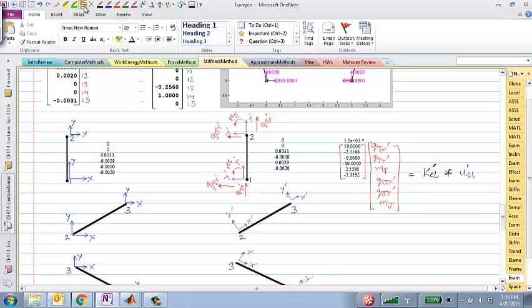Okay. So now that I have these 6 element forces and moments, how do I determine what is axial force, what is shear force, what is bending moment for this element? Is this Q I x prime and Q j x prime? They should be related to axial force, right? So which one is positive axial force? Which one is negative axial force? Right. So j x prime right here. Yeah. So j x prime is the positive axial force.